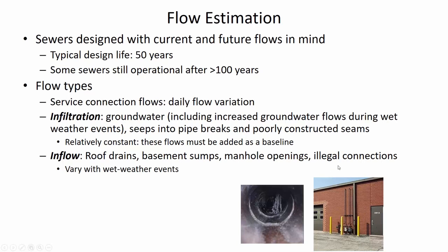The roof isn't polluted. But if this is being discharged to the sanitary sewer, which is going through a really lengthy process of biological treatment, then that can add a lot of additional cost to the treatment, just the additional volume. Even though it's diluting the waste constituents a little bit, still the majority of the cost is related to moving the water from place to place and aerating the water, and not so much related to the concentration of the pollutants in sewage. So both of these are bad things. It's just better if people allow rainwater to discharge over their yard to try and get the water to seep down into the soil with grass.